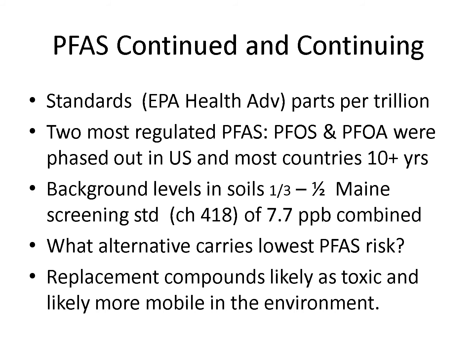So really what the preparer of biosolids needs to do is to show that after utilizing either the compost or the Class B biosolids, the level of PFAS remaining in the soil after use will stay below that combined 7.7 part per billion. Sometimes that's kind of hard to show, but we're doing our best to work through that.